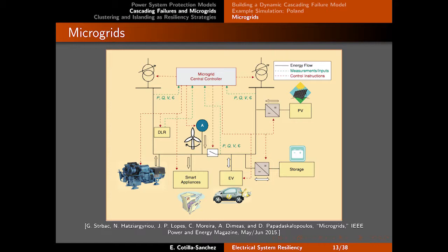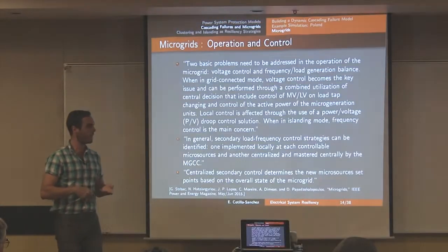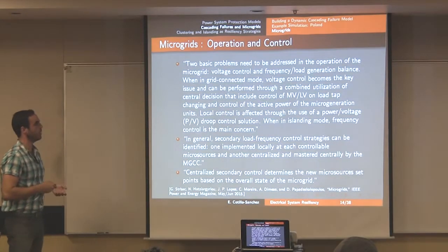Now it seems that you have to zoom in and see how each one of the elements of that microgrid is going to behave. So just to have in your mind, how many extra equations do I have to add, right? Do I have the controllers from my exciters, from my governors? Do I have all my controllers from my relays? Now I need to think about how many equations I can add for my microgrid central controller, for example, to see what voltage output I'm putting out from that microgrid when it's being islanded. So just a little bit of thinking about what the computational complexity is.